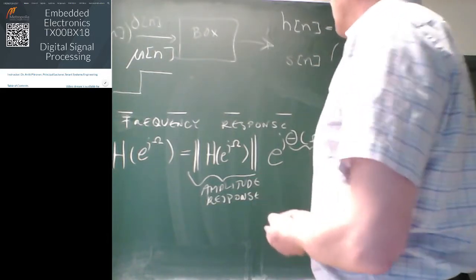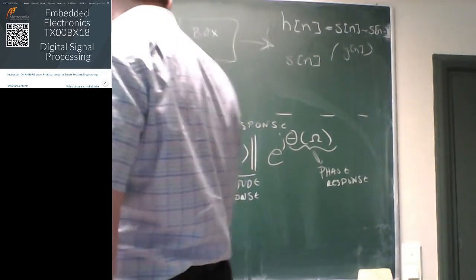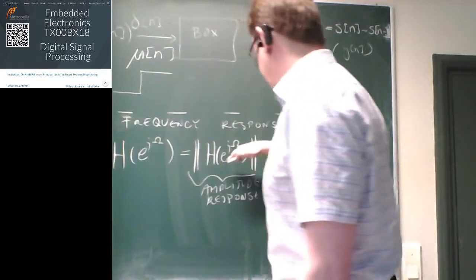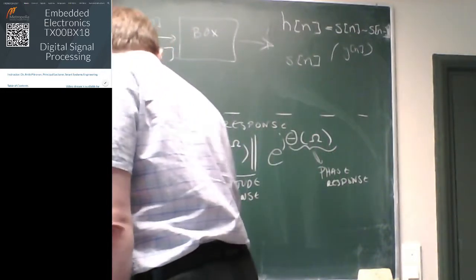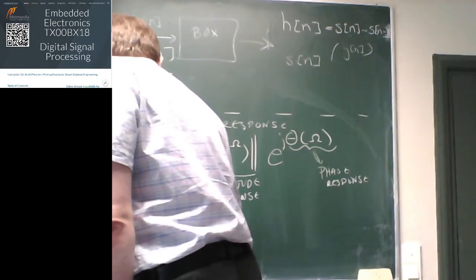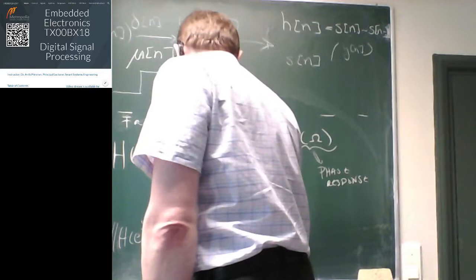Okay, good. So if you take a look at the zeros and poles of the system, then you can also make another form of the amplitude response. Let me mark it down here. So the amplitude response part, at e to the j omega, think of the product form of the transfer function.